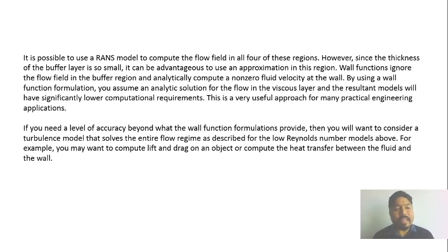If you need a level of accuracy beyond what the wall function formulations provide, then you will want to consider a turbulence model that solves the entire flow regime, as described for the low Reynolds number models above. For example, if you want to compute lift force or drag force on an object, or compute the heat transfer between the fluid and wall.